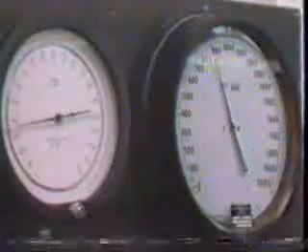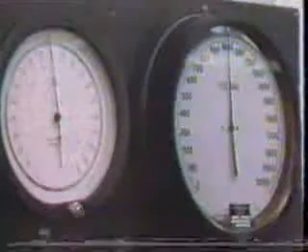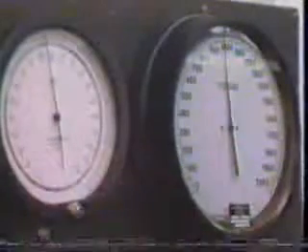There's about 450 pounds. Then I will continue back up with the casing pressure. 700, 750, 800, 900, 950, 1,000, 1040. The valve opened at 1040 with a tubing pressure over here of about 300 psi.